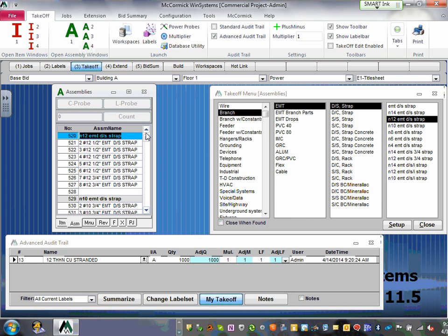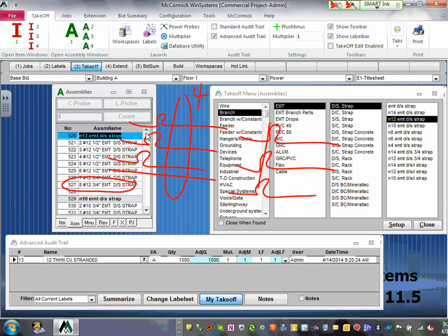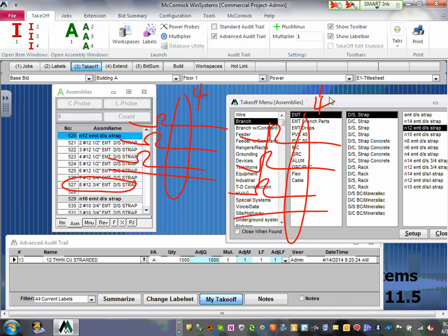Remember, you're taking 3/4 of an inch, and we're going to take, say, 8 conductors. 8 conductors, guys, will give you the following. Let me draw 8 conductors. 8 conductors, Adam. Here's what you get for 8 conductors. You get 1 circuit, 2 circuits, 3 circuits, and a neutral. This is 4 conductors, and 1 circuit, 2 circuits, 3 circuits, and a neutral, and that's another 4 conductors. You can see what you get. How many circuits can you get out of 8 conductors? How many circuits?